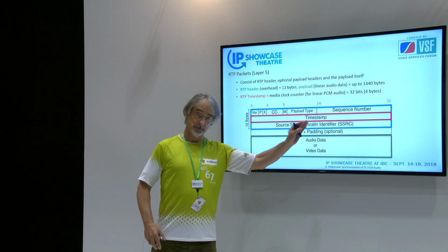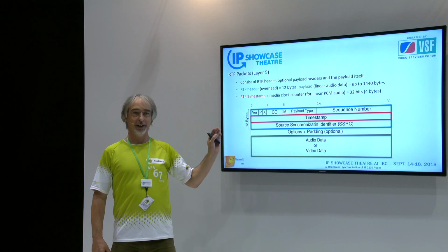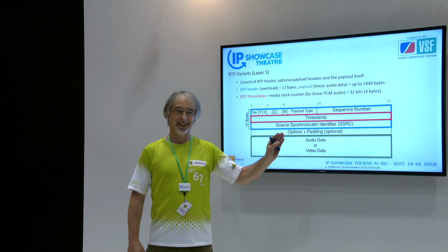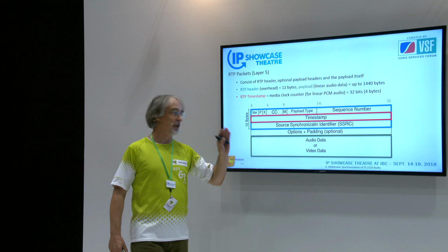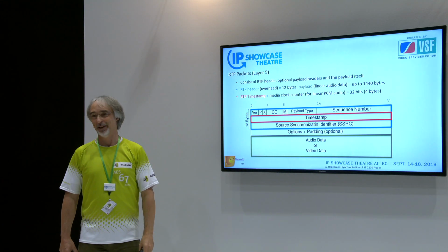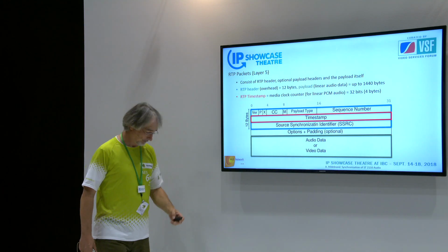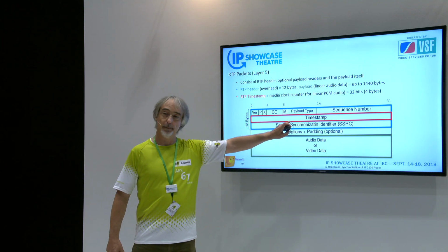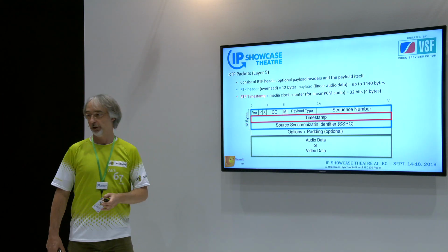If we see a clock count, when had the stream been generated? And believe me, no stream is ever longer on a network than 1 day. So this always gives you a very unique identification. When has this particular sample, which is the first one in the packet, been generated? No stream runs for 1 day on a network. So this is a very precise and very straightforward scheme. So that's how the relationship of that particular packet with respect to system time is being transported.